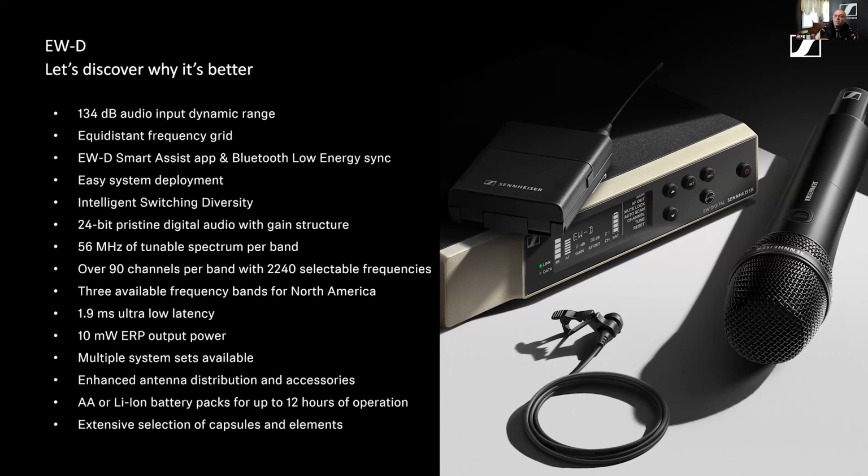When you're in the middle of a show, there's really nothing you can do, other than maybe tell people to try to stay further away. Otherwise, you'd have to do a full frequency coordination. You have to stop the show, bring everybody in, and resync all the transmitters. So you really have to make sure that you either set up that frequency coordination properly before the show starts, or just have a system that doesn't have intermodulation, and then you don't have to worry about it.